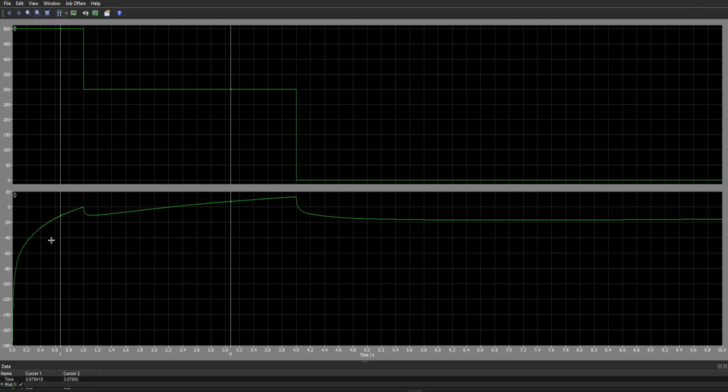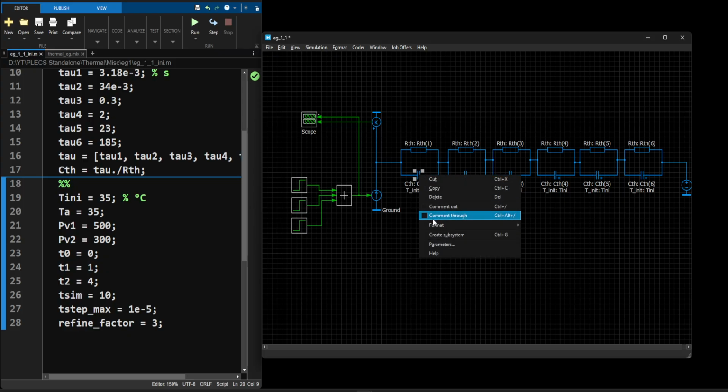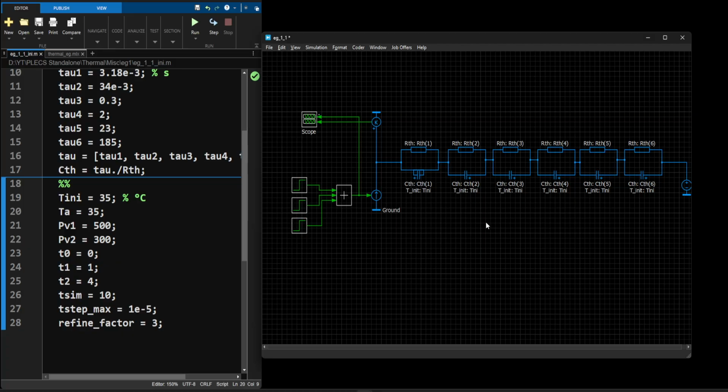So I think this is a direction of measurement, but does it make that difference? Most probably. Let me check. Okay, the orientation of thermal capacitances seems to be making a problem. So we need to change the orientation.